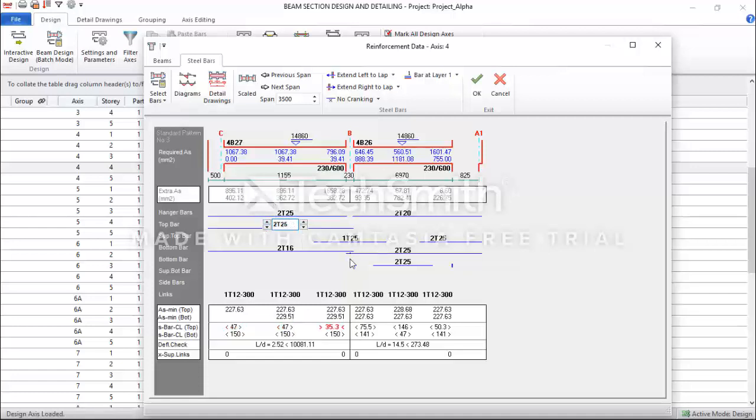But I've not corrected my spacing problem here. So what I'll do here, I will increase the reinforcement at the bottom to 25 and remove this single reinforcement. I think if I reduce this to 20, it will still be okay. The spacing, 20 and okay, 25 will be okay.